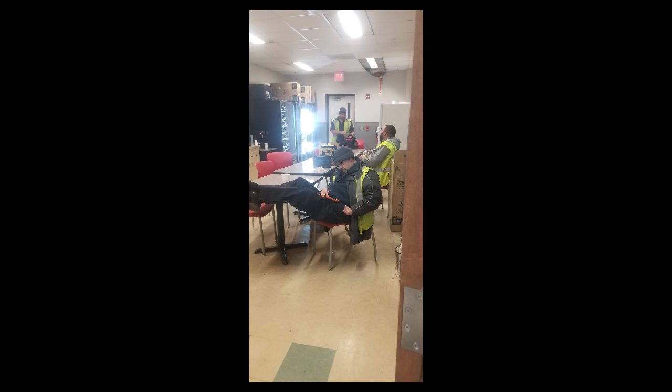49. A certificated mechanic with at least an airframe rating may perform inspections and function checks on aircraft instruments. 50. Which of the following operating mechanisms would be found in a hydraulic pressure gauge? A Bourdon tube. 51. At sea level, when the average atmospheric pressure is 14.7 psi, the barometric pressure is 29.92 inches Hg. 52. Which of the following will cause inaccuracies in a magnetic compass that may be compensated for by an aircraft mechanic? A. Deviation.